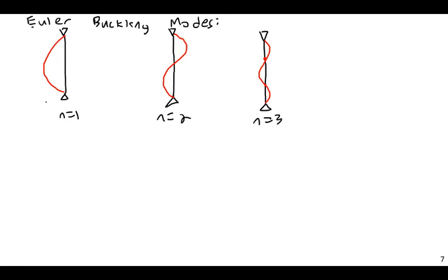Euler buckling is an idealized case. It's looking at purely idealized elastic behavior. You're not dealing with any kind of local failure. You're not dealing with any kind of global failure. I guess Euler buckling is a global failure, but you're not dealing with any properties of the section itself, really, beyond just moment of inertia.